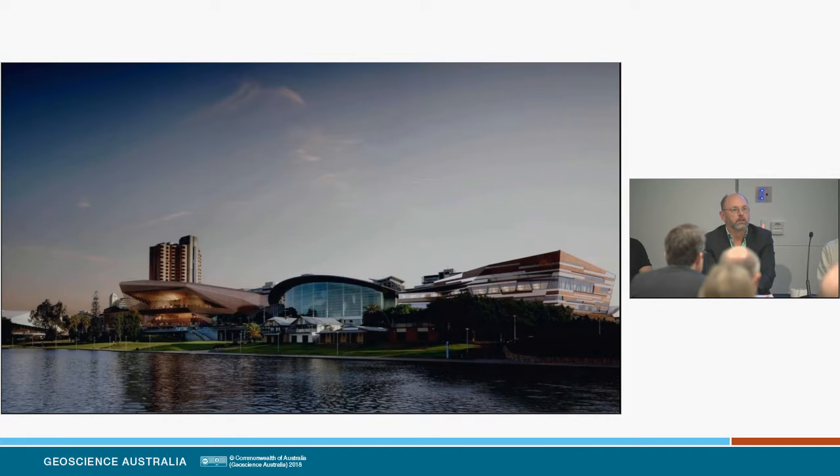The other approach is if you're doing a survey where somebody's looking for shallow, small targets, diamond exploration, for example. They're not interested in the long wavelengths. They don't really care to collect or have long wavelength data in there, and we just filter that long wavelength from the data before we process it. So we're filtering out wavelengths that are longer than the survey area in that situation. Petroleum exploration, the long wavelengths are absolutely important, so you would definitely be conforming external gravity into the data. And that's been routine processing for many years now in Falcon data.